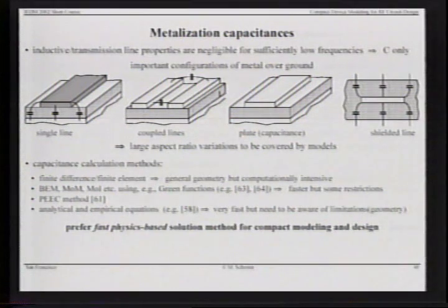This just shows a bunch of structures and is supposed to visualize the various different capacitances that we have to model by lumped forms, by equations as a function of the geometry of these conductors, the oxide thickness, and also, of course, a function of the resistivity of the substrate if there are series resistances. But I want to just talk about parasitic capacitances. And there are capacitance solvers, very fast solvers for the electrostatic problem. What we are looking for in compact modeling, because it has to be implemented in circuit simulators, are very fast, compact